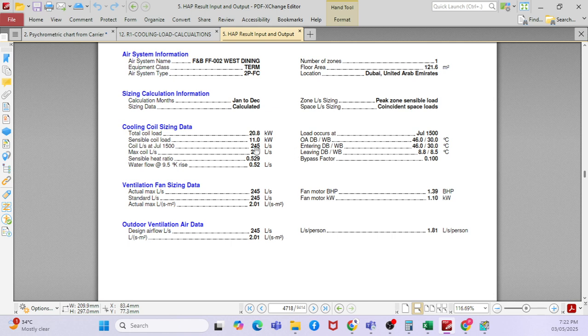So that is the coil temperature. How will we determine the coil inlet temperature and outlet temperature, right? For thermal comfort, based on the ASHRAE standard, the supply temperature should be 5 degrees Celsius or 6 degrees Celsius, and the return temperature should be 12 degrees Celsius or 13 degrees Celsius. That is what we normally follow. That is the supply temperature and return temperature.